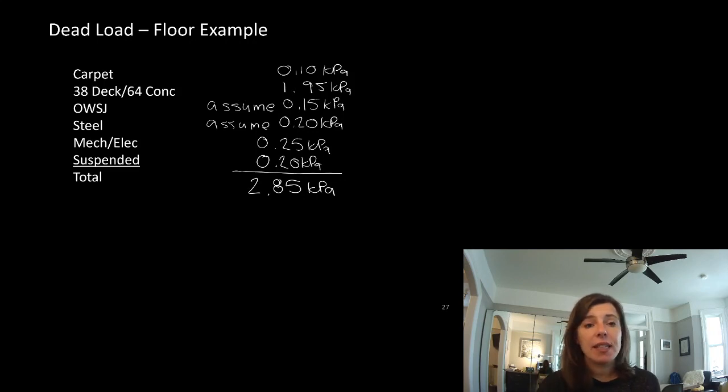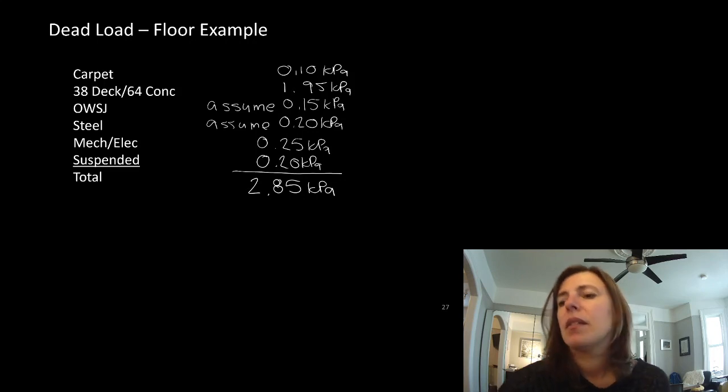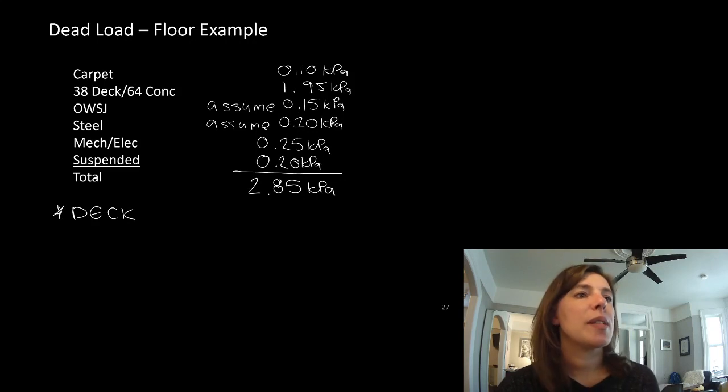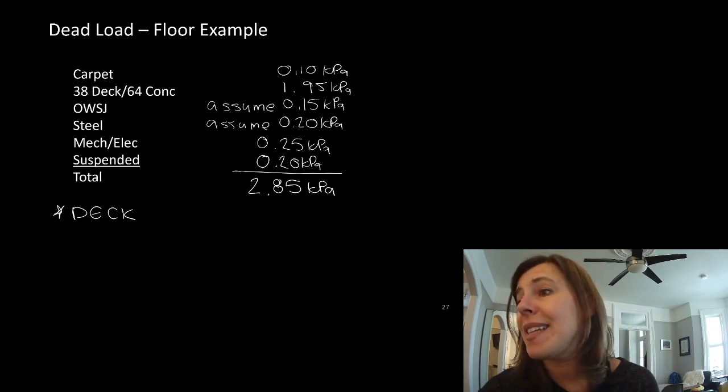Great. Let's do the same thing that we did and just break out what our decking assembly is supporting and what our joists are supporting. In case we needed to design those, we can make use of the lighter loads for designing them because they're not supporting the things that support them. So let's pull out all the things that the deck supports.